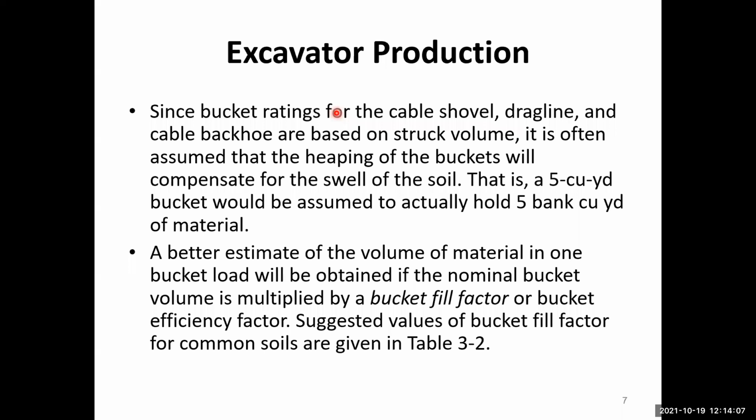However, in practice, when the bucket is used for digging the soil, the soil will heap over the bucket. So in that case, an assumption can be made that the heaping of the bucket will compensate for the swell of the soil. That means whatever the soil swells, as a result of the swell there will be some heaping of the soil, which means that the heaped volume of the soil may be the same as, or maybe more than, the bucket volume.